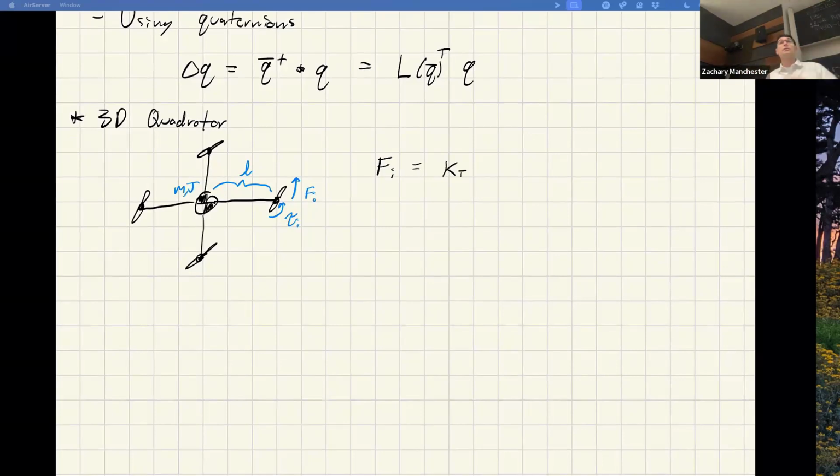So for us, we're going to, yeah. This is assuming a massless propeller, right? Because you're not worried about the moment of inertia. Yeah, we're not going to model it here because it's sort of in the noise, but you could for sure, if you wanted to build a really high fidelity model. Frankly, there are aerodynamic terms that matter more than that usually, but you're 100% right. There are definitely gyroscopic effects from the rotating propellers. But typically, yeah, this is the model.